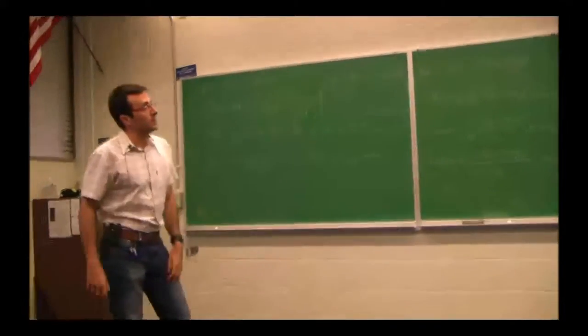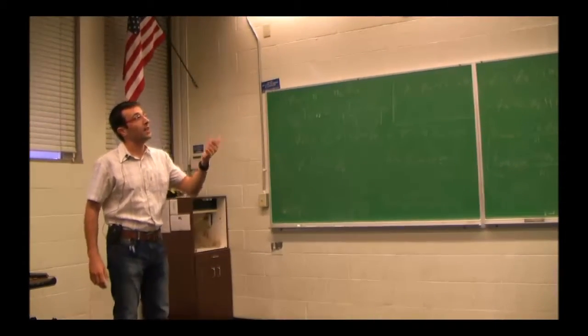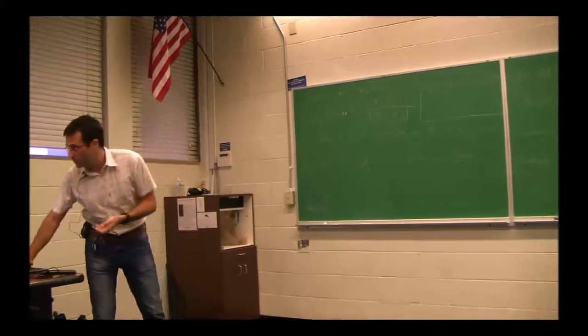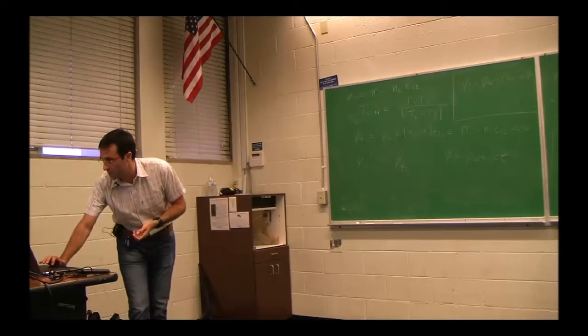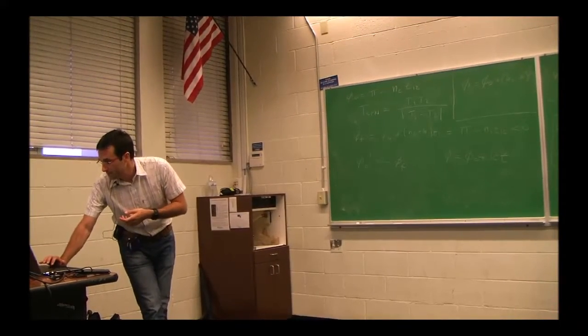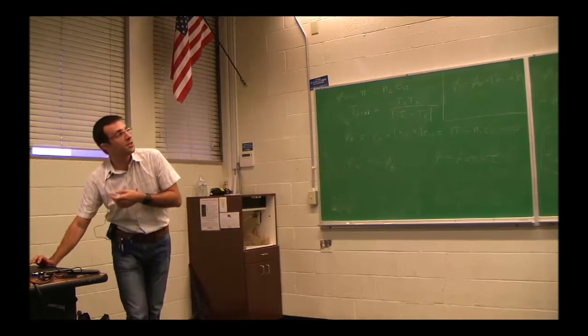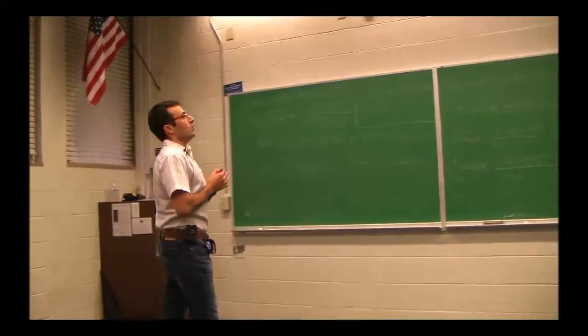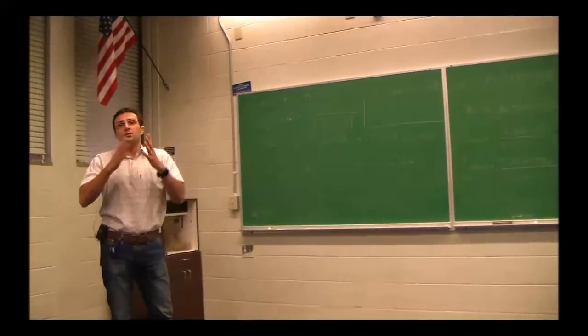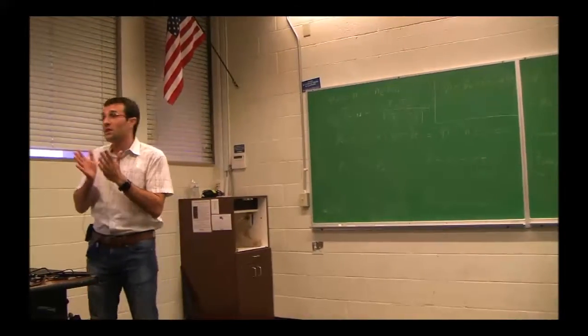Okay? So if you add all of that together, the t wait and twice the t12, I hope it's clear why it's twice, because I am going and then coming back, you get what I showed you last time, these 2.666 years. Now, we're not going to cover alternative ways to get to Mars, which is of interest these days,